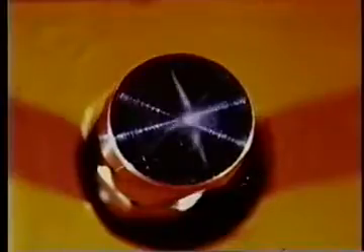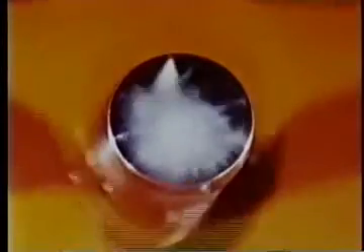We are looking directly upward at the face of the specimen. The total amplitude of vertical oscillation is only 0.02 of an inch, but the pressure is changed from below vapor pressure, as the button is accelerating upward, to a high pressure, as it is accelerating downward, at the rate of 14,000 cycles per second.